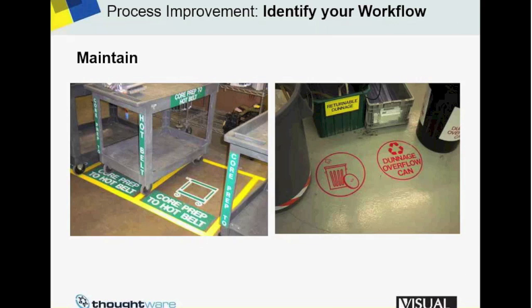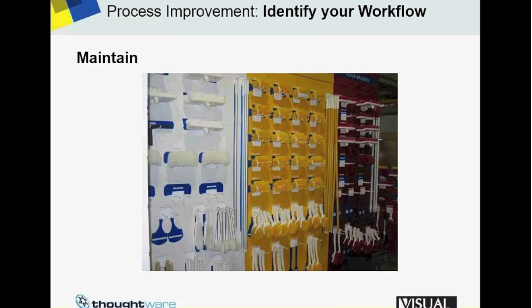We want to identify corresponding gauges, control charts, check sheets, diagrams, overlays, calibers used, everything we need to measure the effectiveness of the process. And in maintain, we also need a way of replenishing parts. We need to determine how to visually indicate the current condition for quick identification with temperature-sensitive labels, see-through panels, correct positions being outlined, color coding, and of course it's critical in this maintenance exercise to involve the maintenance department.